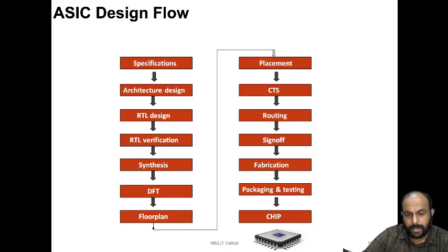There are a variety of methods employed for that, and languages like Verilog, and more prominently SystemVerilog, are used here for verification purposes. Verification is essentially checking the conformance of the design to the specification, independent of the designers. The designers have already understood the specification and designed something, but they might be missing certain corner cases, certain examples of inputs upon application of which the design may malfunction. So the work of the RTL verification engineer is to debug the design at a much more exhaustive level that is not possible at the design level.